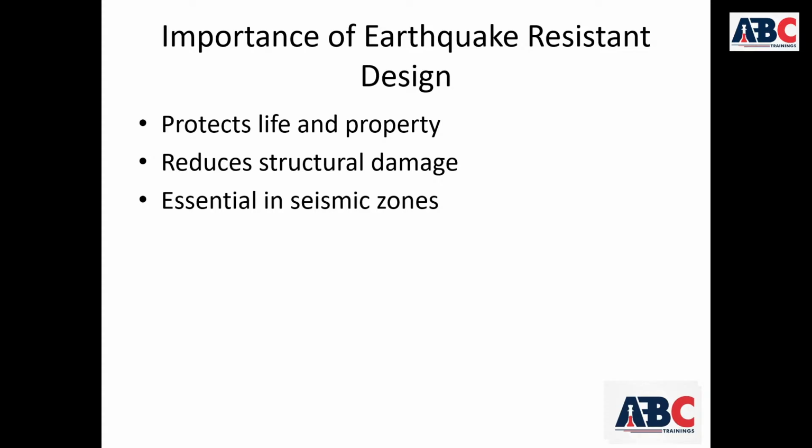Next is reducing structural damage. Earthquake resistant buildings are designed to withstand lateral forces. These structures are properly reinforced, carefully detailed, designed with ductility, and provided with a proper load path. Such buildings may develop cracks during strong shaking, but they are designed to avoid total collapse.